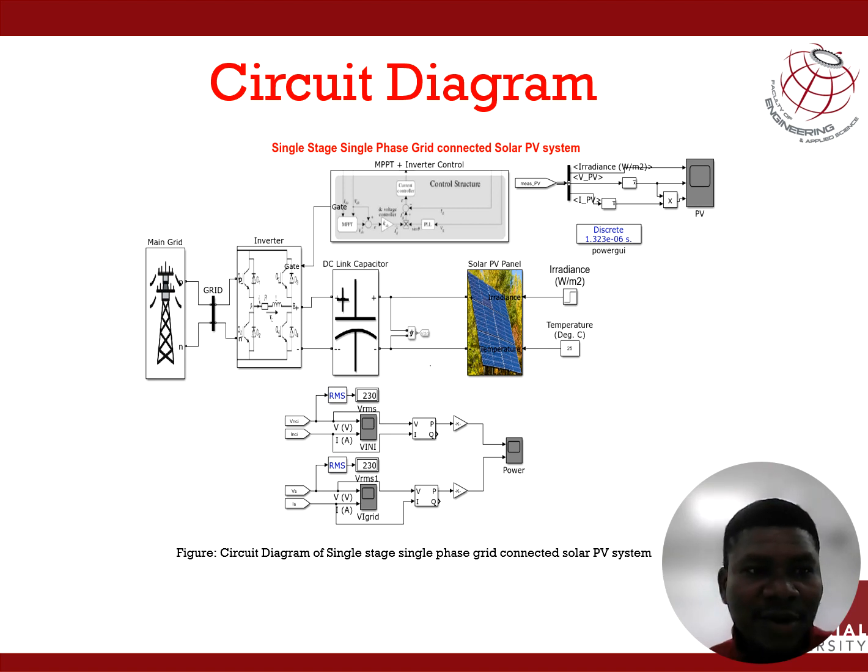We also have our maximum power point tracker, MPPT. The DC output from the combiner bus is then fed into a maximum power point tracker MPPT controller. The MPPT is a critical component that optimizes the solar panel's output by continuously adjusting the voltage and current to maximize power extraction from the panel under varying weather and temperature conditions.